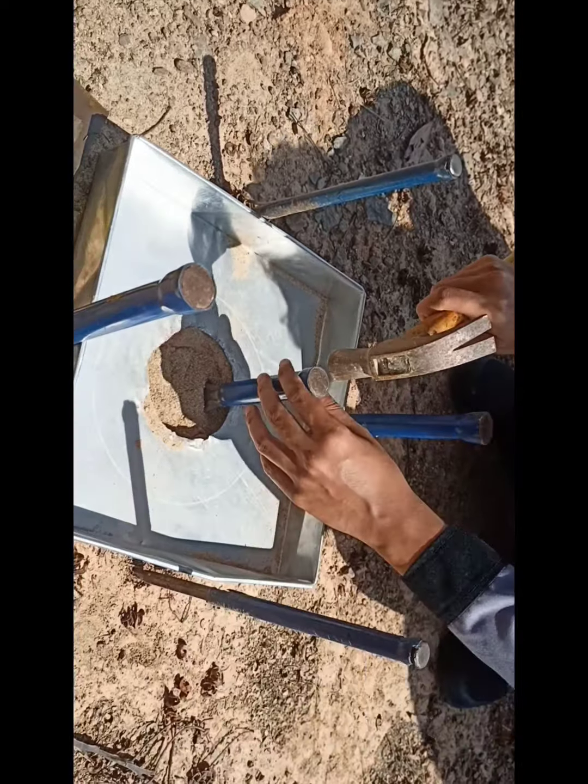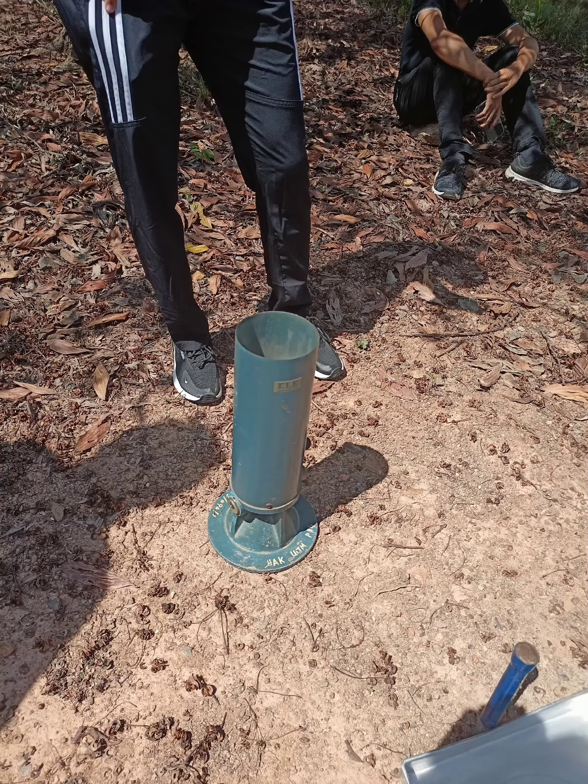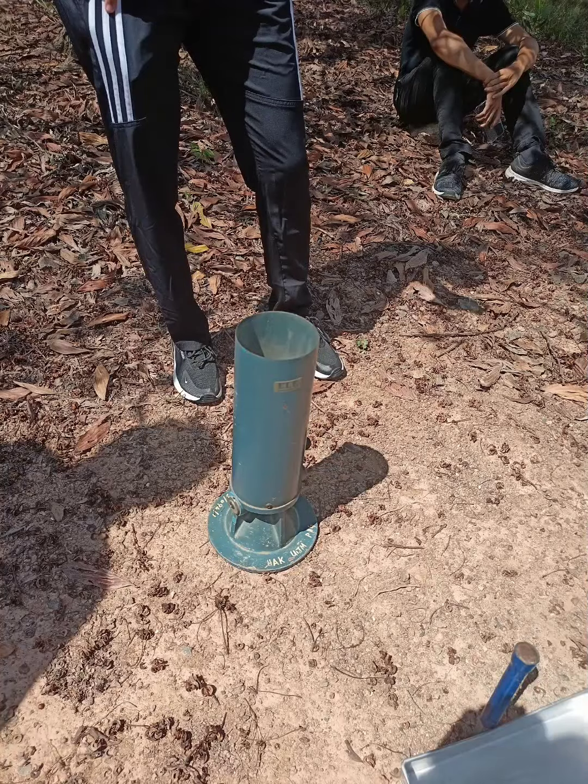The metal tray with the central hole is removed and the sand pouring cylinder is placed centrally over the excavated hole. The shutter is opened until the sand fills the excavated hole and the cone completely, until there is no further movement of sand in the cylinder. The shutter is closed and the cylinder is weighed so that the weight of sand filling the excavated hole alone can be found.